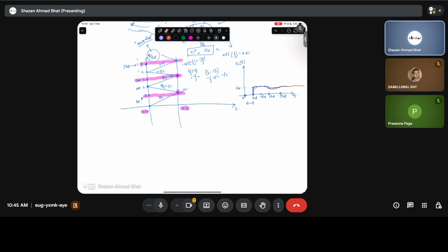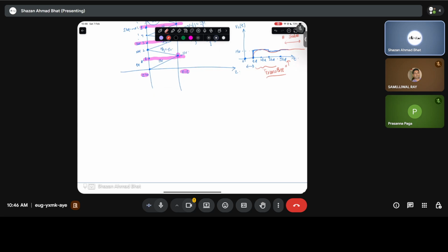It's sort of an initial transient, which is time varying initially. It's basically not a stable response, and then it tends to a stable response. It's something you might have studied in control systems as well. After a certain time constant, which is 5 TD or 6 TD around, it depends upon the system, and also upon how much the reflection is. Yes, it definitely depends upon the impedance mismatch. So that is the response of this particular system.